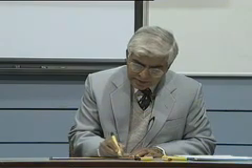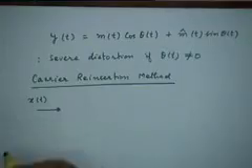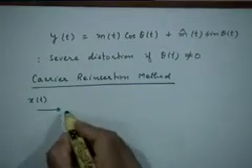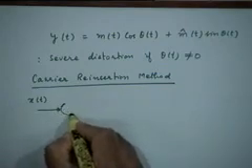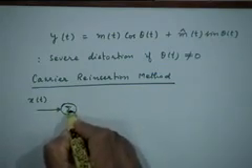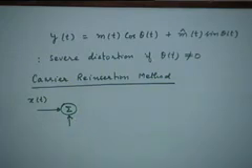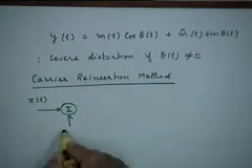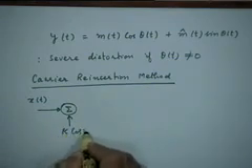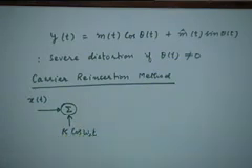Basically here what we do is take the incoming modulated signal, and instead of multiplying this with the local carrier, you simply add the local carrier to the incoming signal.